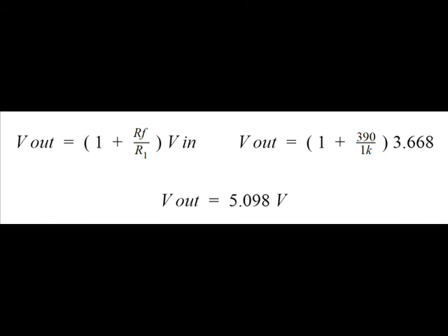We had a lot of complications in the physical implementation, but we expected our oscilloscope measurements to coincide with the theory calculations. We did not consider the losses by the load, and the losses by the magnetizing current, the wire and the core. This situation forces us to add components not provided in the original design to meet the necessary requirements in the project.